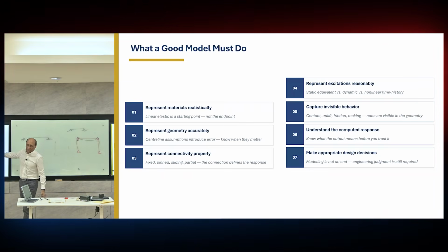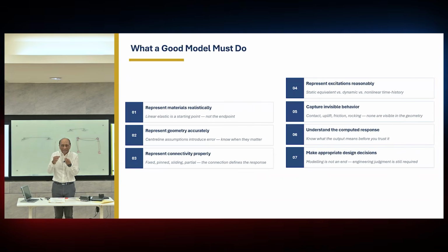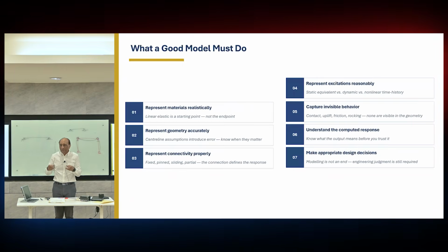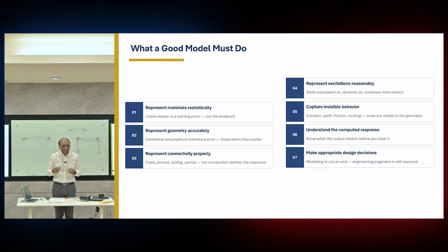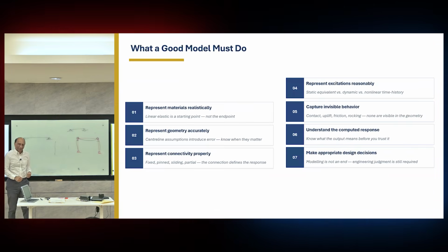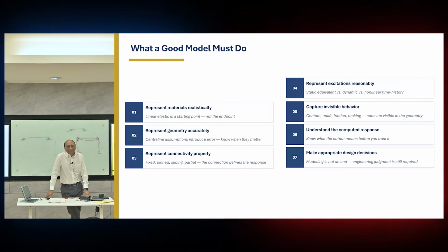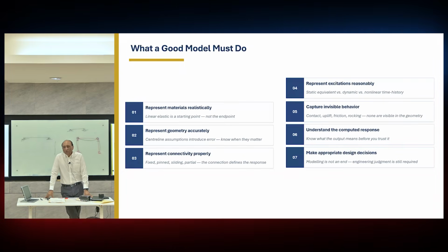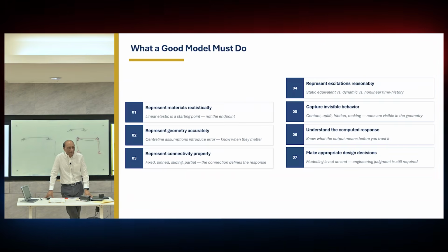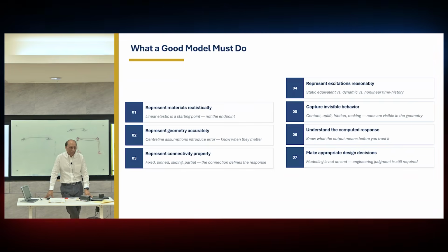Capture invisible behavior. This is very important. Capture that invisible behavior of sliding and falling off and toppling. Those are invisible behaviors. Try to capture them. Friction, uplift. Understand the computed response. So, like I said, shell element does not give you stresses, but you do need bending moment. So you need to then do some more computations, put some section cut, integrate the stresses to get the moment back. Solid element also, you need to integrate the stresses to get the moment back.